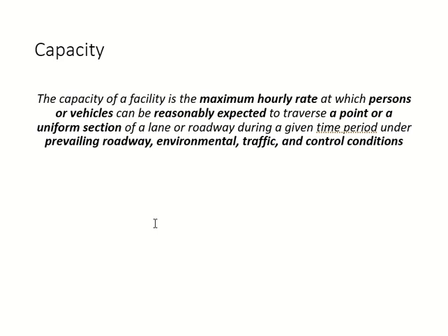The manual deals with highways, so the capacity is in vehicles per hour for those highways, and it also deals with public transport facilities like bus services and train services. So in those cases, the capacity will be persons per hour. And capacity is a reasonable expectation. So according to the design of the highway, we expect the maximum flow rate to be this much. The actual can be a little bit high or low. So this is the error. You need to expect it.